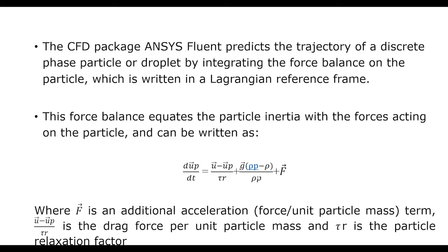And this is a pressure force. There is also pressure force and also additional forces. These additional forces, in this case, may actually be Saffman's lift force, which are due to shear, or Magnus lift force, which are due to rotation. All these things will be considered, but depending on the problem, this F may incorporate different setups.